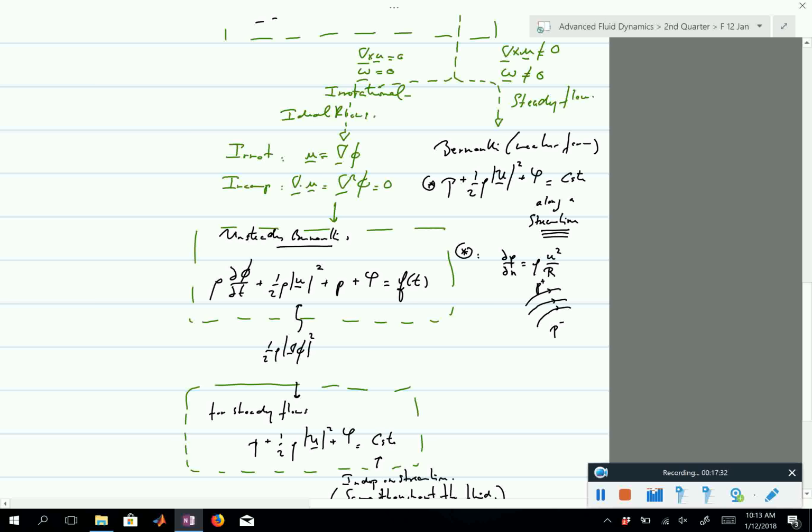In the fluid, you need a difference in pressure, a difference in force, to change the momentum or change the direction of the flow. If the flow is bent this way, that means you have a piece of mass that is moving towards the bottom. So the direction of the momentum is changing, and it just feels a net force in this direction. So that means you need to have more pressure here than here. Okay. So always remember that.